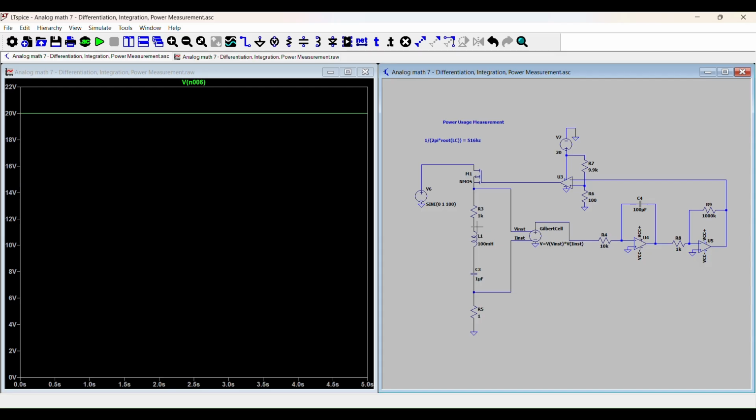So the only time when it could be out of phase is when there are reactive components. And if it swings negative like that, it's basically the reactive components dumping energy back into the circuit. So when you sum it all back out again, it actually does equal the true power dissipation, which is very surprising to me. But yeah, the mathematics works, and it does make intuitive sense after you think about it for a while.